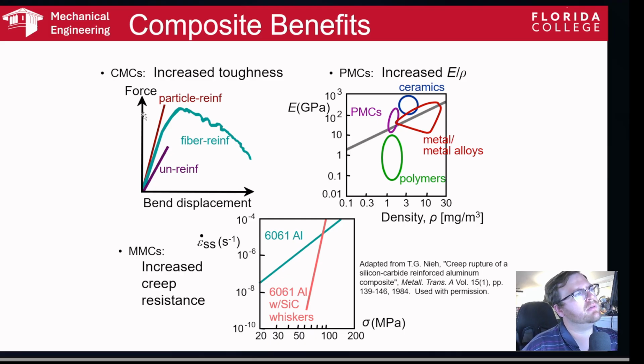And then you have your particle reinforced. Okay, here your particle reinforcement actually does not help a whole lot with making the material fail more gracefully, but it does add a lot of stiffness, and it does increase your yield stress. Okay, which means right after you yield, you break, because ceramics, heavily stiff materials, they don't tend to give you an ultimate tensile stress following yield because they just break at yield, usually.